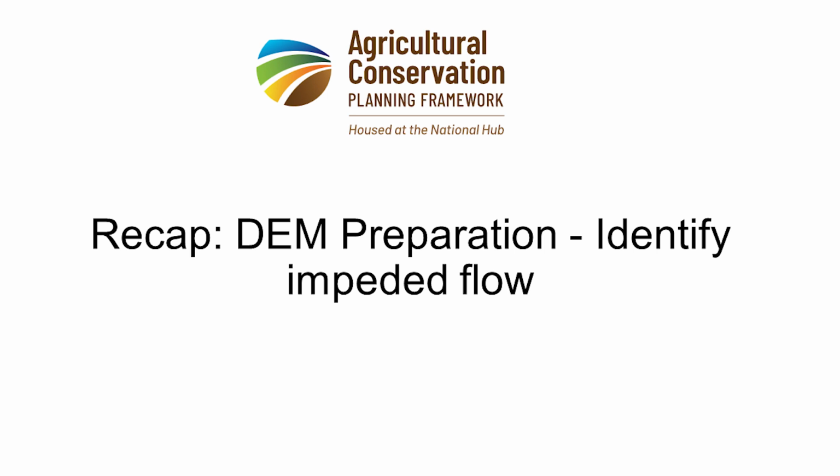In this video, we discussed some of the considerations to think about before beginning the hydro conditioning process. We also ran the Identify Impeded Flow Tool using our DEM. The Identify Impeded Flow Tool is the first of 3 steps in an iterative process to hydro condition our DEM.